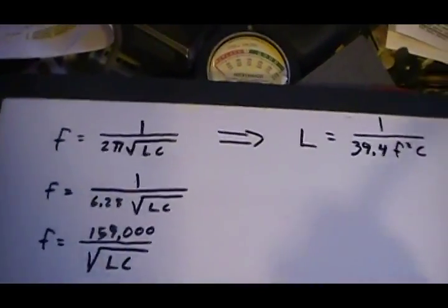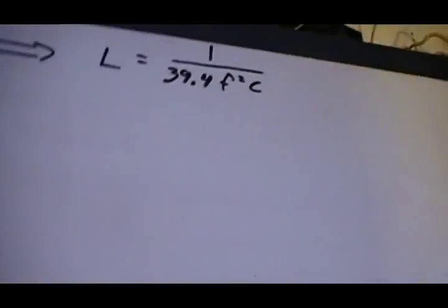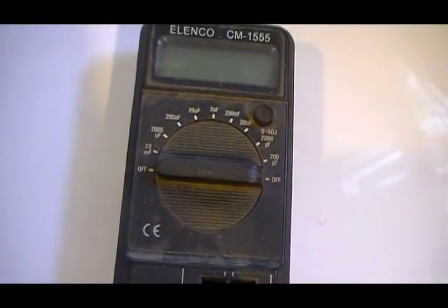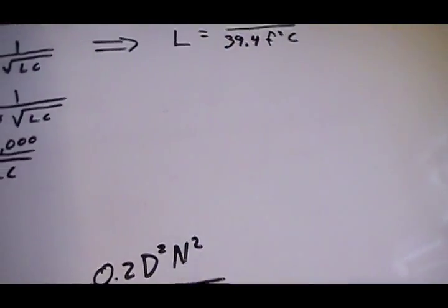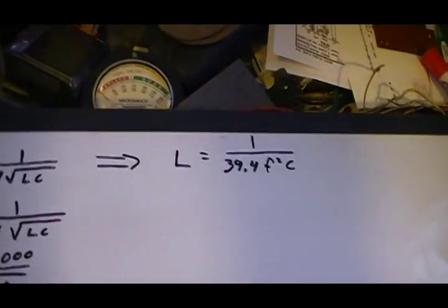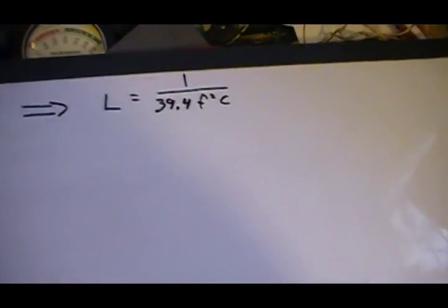Usually the case, you know what the capacitance is, because, I didn't stage this too well, but to measure basic capacitance, like a tuning capacitor, you can use something like this, just a cheapy LC capacitance meter. That's all. It's fine for measuring a tuning capacitor that you're going to use in a generator. So in a case like that, now you know the capacitance, but most people don't have an inductance meter to come up with an inductance.